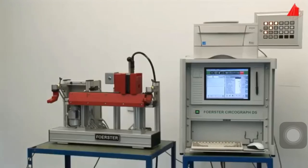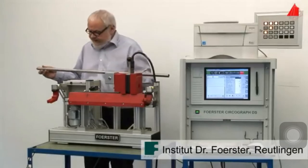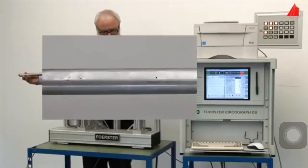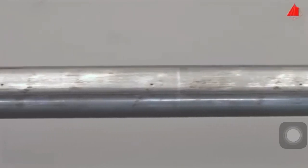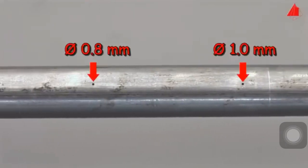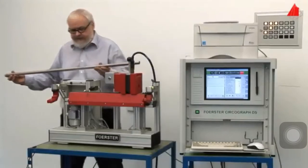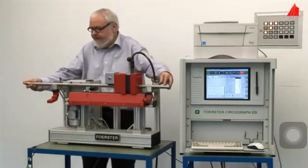If the coils are optimized even further, much smaller defects than our large saw cuts can be detected. This tube is made of a non-magnetic austenitic steel. 4 bore holes have been drilled through the tube, starting with a diameter of 1.4 mm and ending with 0.8 mm. Now, instead of performing the test by hand, we prefer to use a mechanized testing machine.